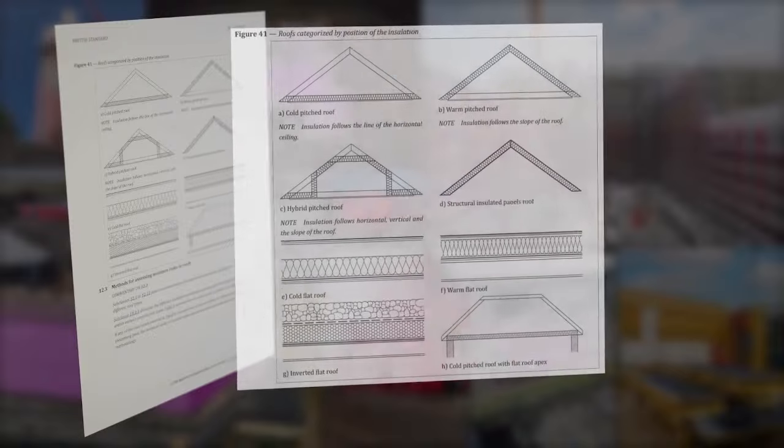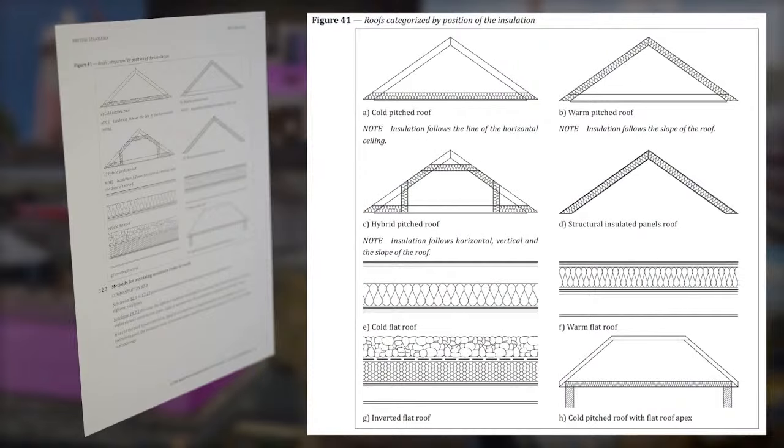The guidance given in BS 5250 to reduce moisture risks in roofs depends on which type of membrane is used and on the roof configuration. If an impermeable membrane, a type HR underlay, is used on a roof, then the roof must be ventilated to allow moisture to escape. This can be reduced or even eliminated if the membrane is vapour permeable, type LR.